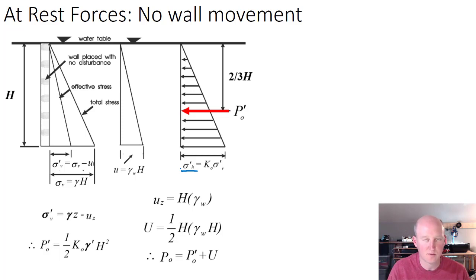And you're going to see some larger equations, and I'll tell you my preference is that we calculate that horizontal pressure at the base of the wall first, and then just multiply that to get the area of the triangle. So 1/2 times that value times the height of the wall. And so in order to get this value, we need to calculate what's the vertical pressure or vertical stress on the soil at the base of the wall. So if we're imagining a unit of soil there, we're interested in knowing what's this pressure, sigma prime sub v.